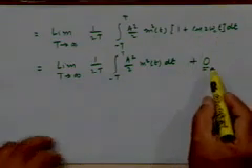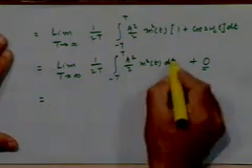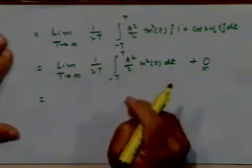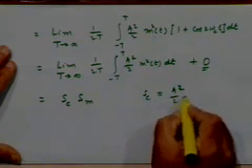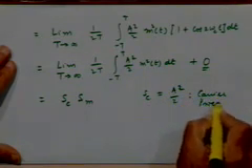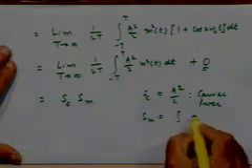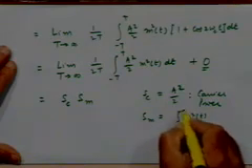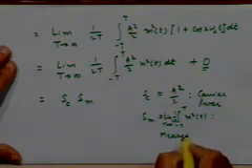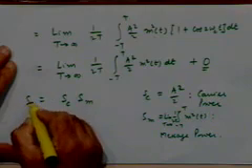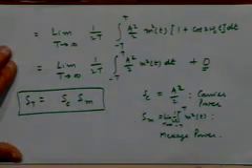Okay. So therefore the second part is the same argument which we have discussed earlier, and therefore what is now, if you take A square by 2 outside, what is left inside the integral? There's nothing but the power in the message signal itself, right. And what is A square by 2? That's power of the carrier. Carrier is A cosine omega ct, its average power is A square by 2, right. So therefore you can think of this as nothing but S_c into S_m, where S_c is A square by 2, which is the carrier power, and S_m is the integral etc. of the message etc., limit as t tends to infinity. That's the message power. So your transmitted power S_t is the product of the carrier power and the message power.